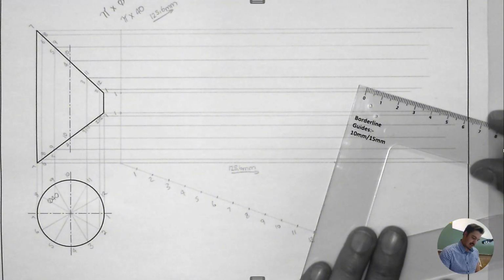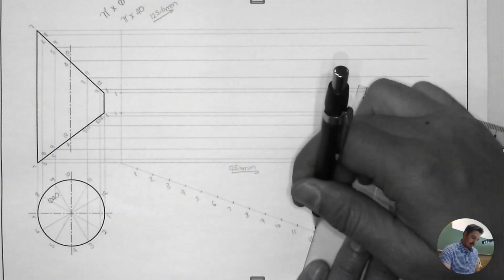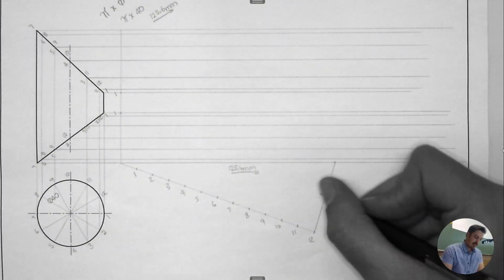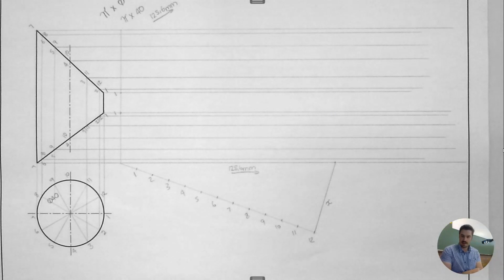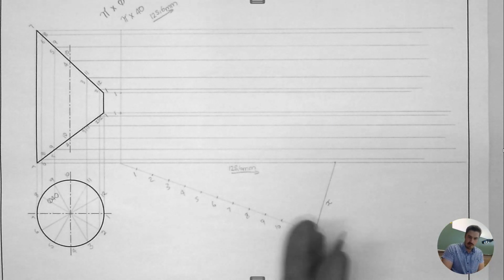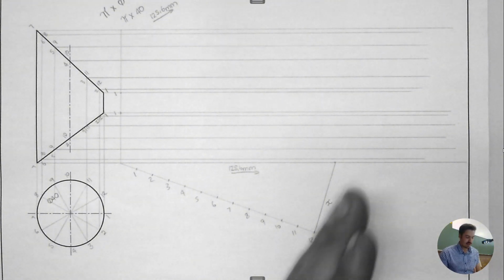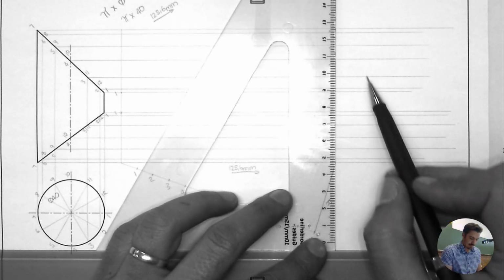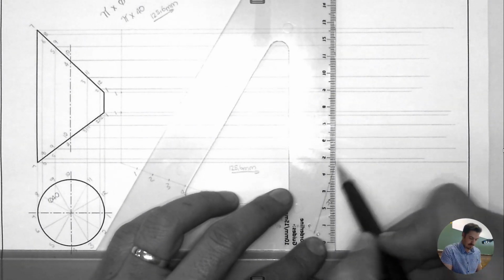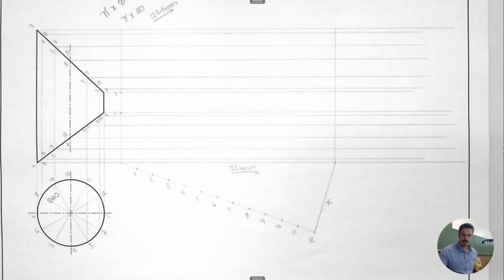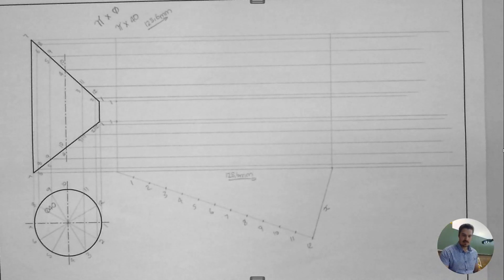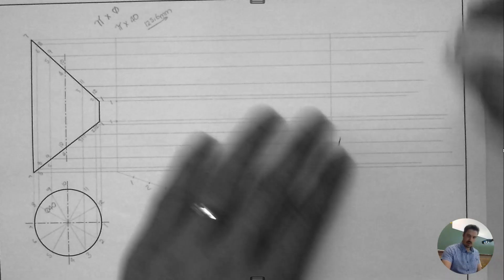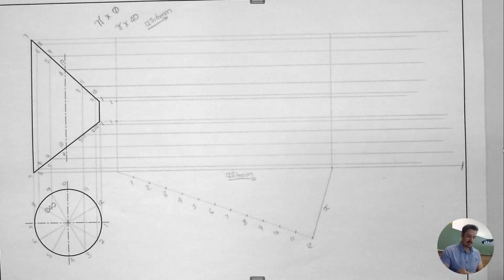So from the last segment that you've made, 12, you draw a line that goes onto there. This line we refer to as X. That's going to be the reference line that we need for the rest, right? So we need to divide this line in 12 segments. So from here, everything that's on the right hand side of that segment is non-existing anymore. So you can either erase it, you can leave it as such. As long as it's still construction, it most likely doesn't matter.